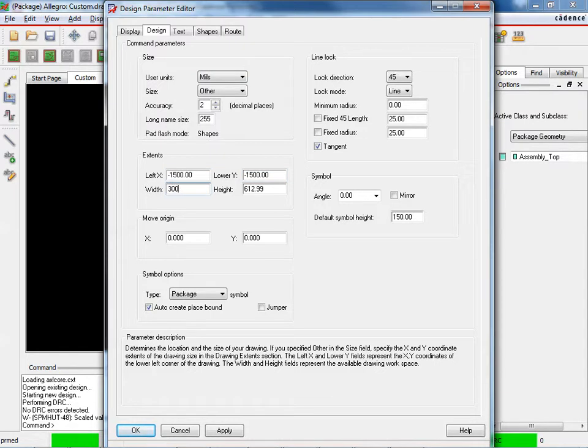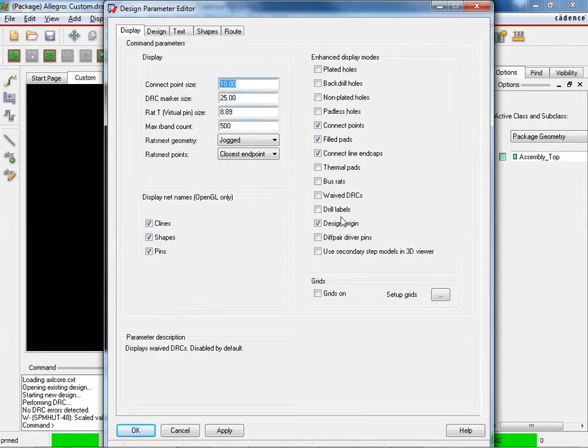and what I'm doing here right now is defining the lower left hand corner and the upper right hand corner of our design, meaning that I can't have anything bigger. Essentially it can't be any bigger than 4.5 inches by 4.5 inches, because 1,000 mils is an inch. So it's plenty big here for us. We won't need all that space. It's fine that we have it.